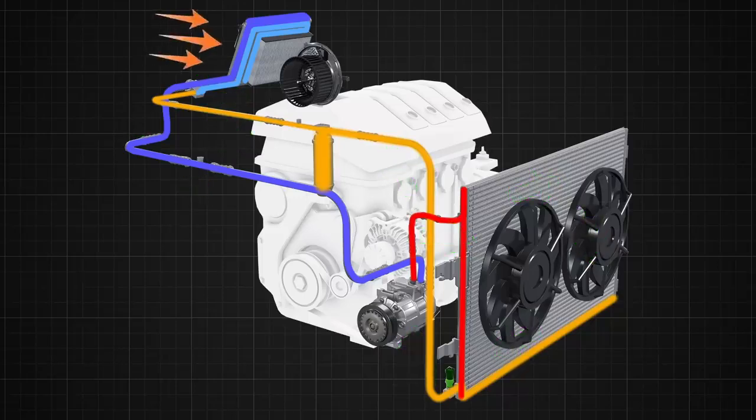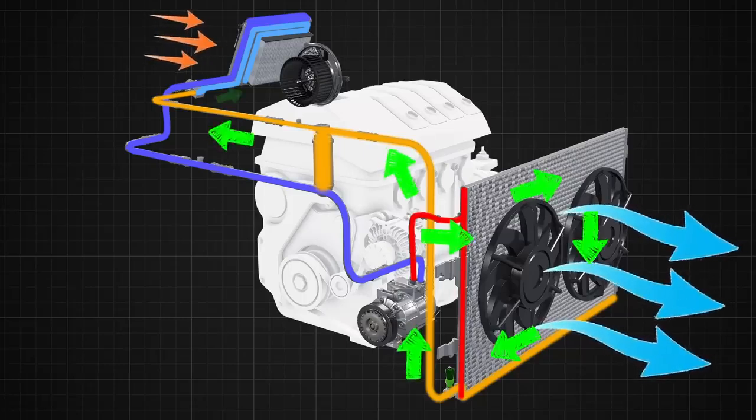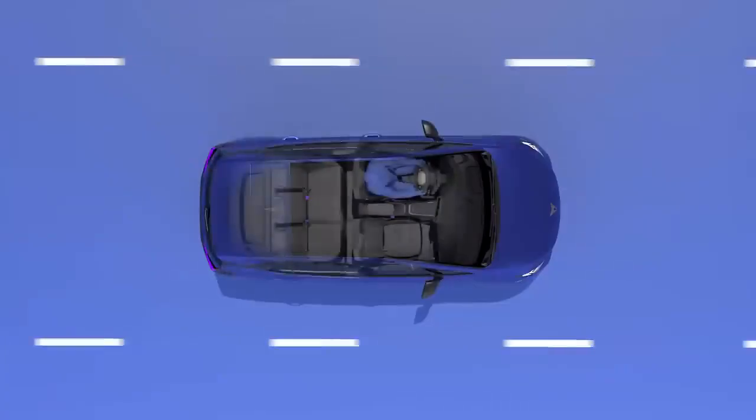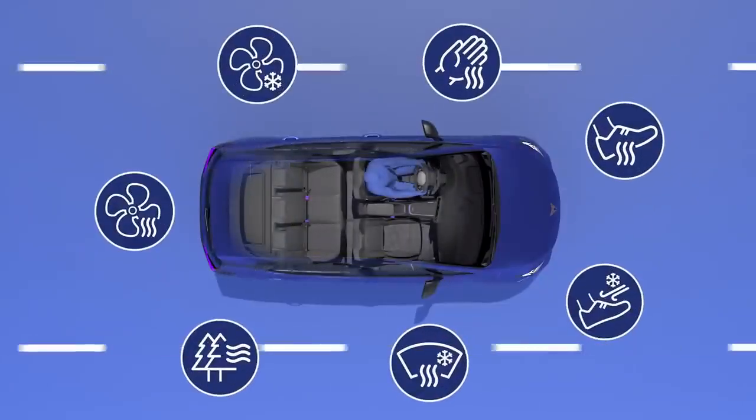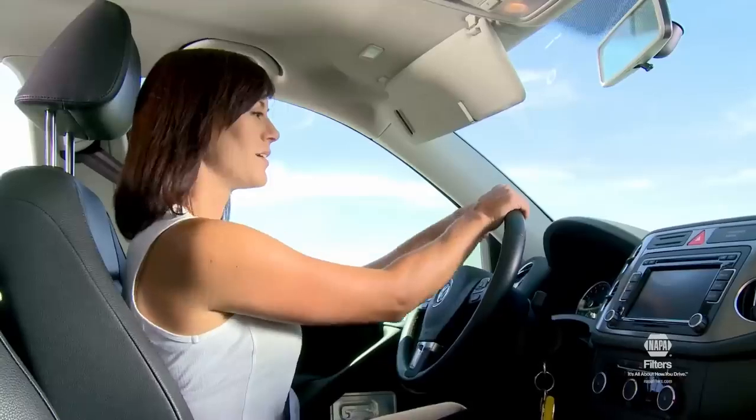With the evaporator absorbing heat from the cabin air, the condenser releasing heat to the outside air, and the expansion valve controlling the refrigerant flow between the two. This continuous cycle allows the AC system to maintain a comfortable cabin temperature and humidity level while the vehicle is in operation.